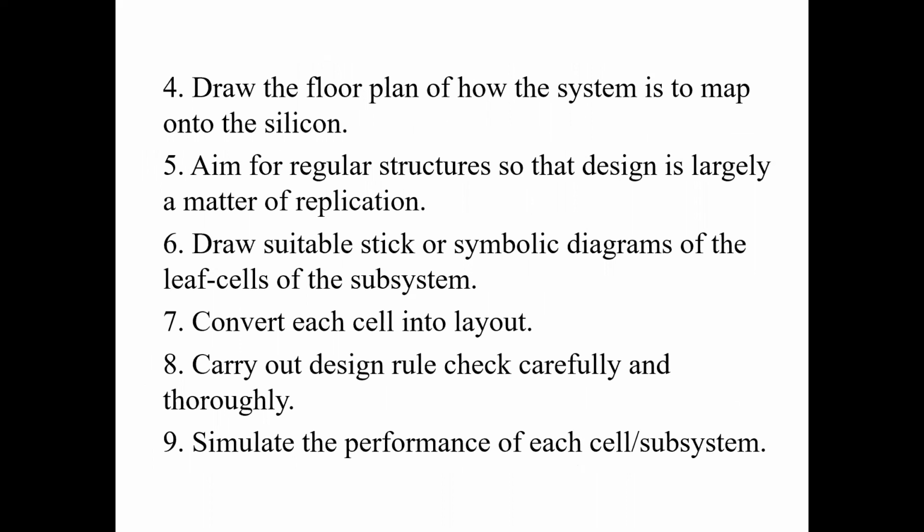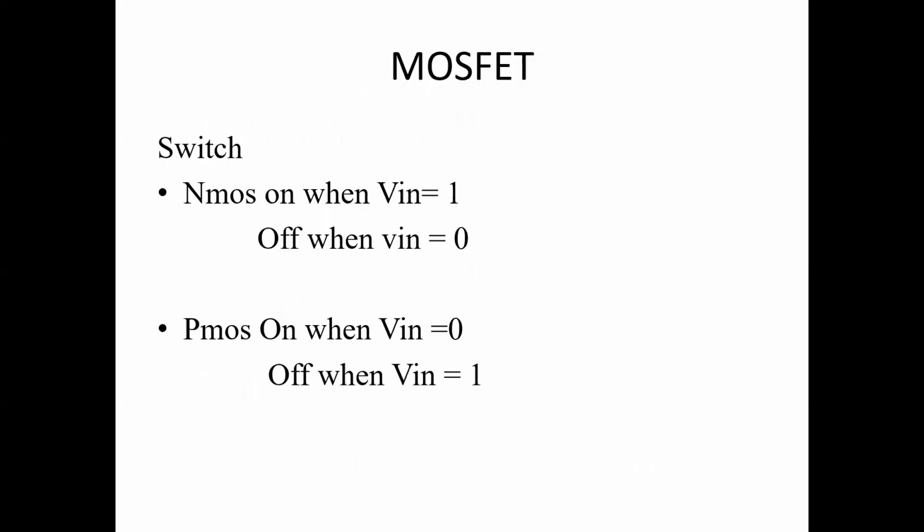That is what regularity is. We have to reuse any circuit or component efficiently, which reduces the time as well as the complexity and cost. Convert each cell into layout and then start designing. Carry out design and check carefully throughout. Using design rules, we have to verify the correctness of the circuit, and finally simulate and see whether the circuit is working properly. So these steps have to be followed whenever we design a subsystem or system.